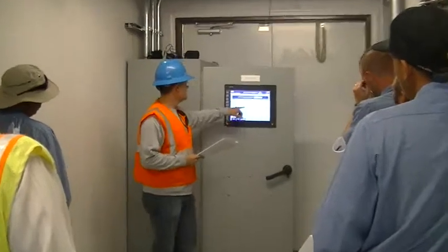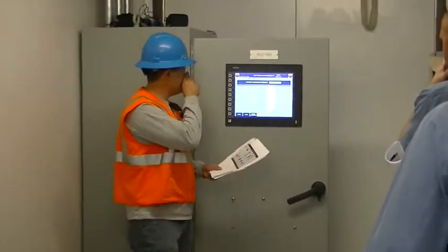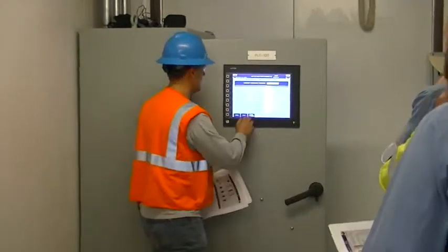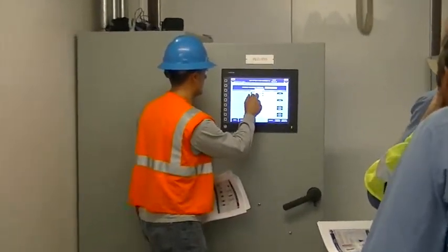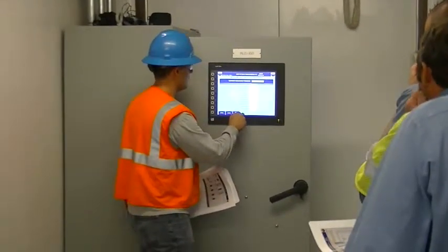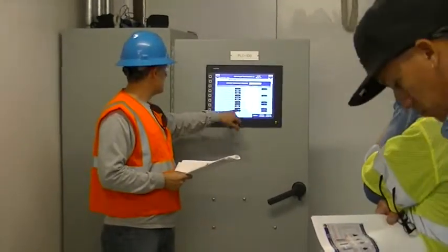So on the regular duty set points, these are the VFDs. Basically how it's set up is you have your lead start pressure set point. Let's change that to 65. Okay, so actually that is going to be 60.